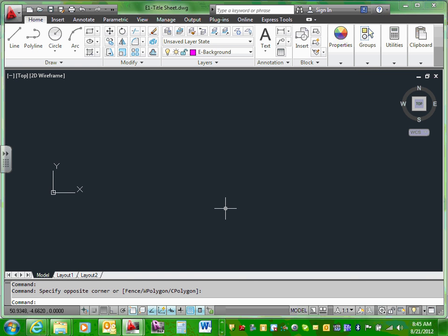Very powerful, right? Because we work in a team, guys, with other colleagues, mechanical and electrical and a bunch of other disciplines. That's what the Xref is. We never work in the file itself. We always Xref the file because architects change their mind. They move a wall. Then in the morning we come, we load our file to work on it. We see that all the stuff that we did has been shifted. Why? Because the architects changed their mind by moving the wall. Is this a good idea? Of course it's a good idea, because when you and architects are working on the same file at the same time, Revit does it much better. You're going to see later on as we do it.